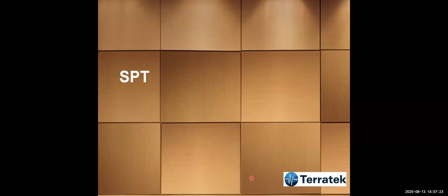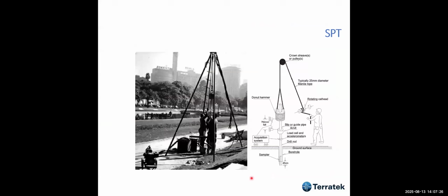I'd like to address first the SPT. SPT is very old, something that took place in the 60s. We just use a tripod, and the SPT, the standard penetration test, is standardized in many standards, certainly in America and Europe, etc., and is used all over the world.